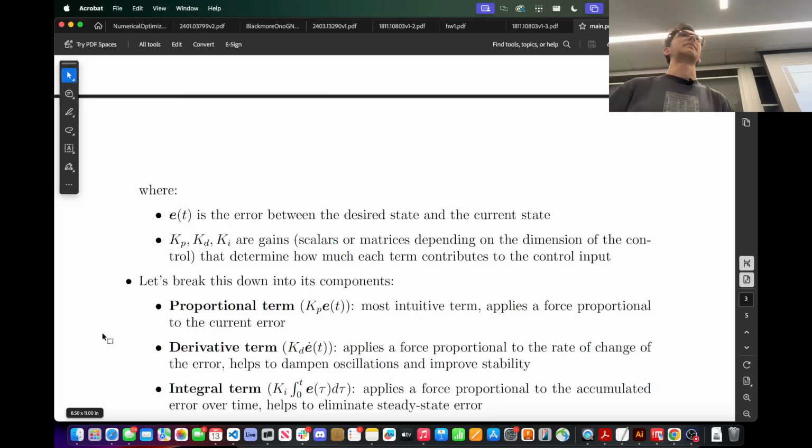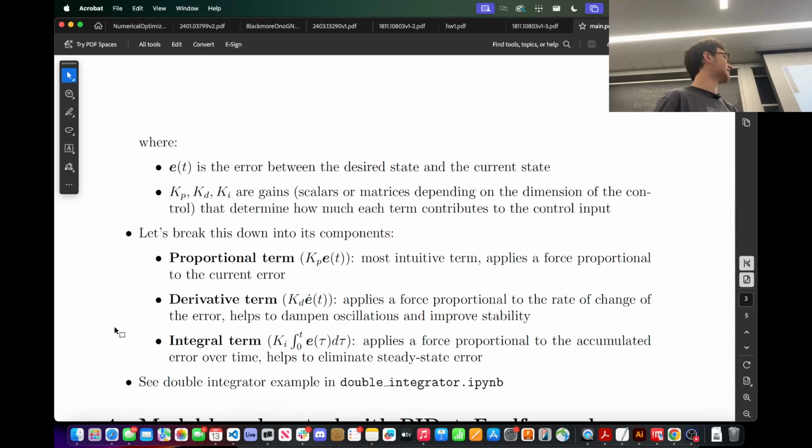You can do a min-max on the integral term. There's a lot of heuristics that people use. You can do a min-max on the actual value of the integrator. You can do what you said, which is you only allow it to act at certain distances or at certain error margins. So yeah, there's a lot of heuristic stuff that you can do if you determine that you need an integrator. But there are some ways that you can try to get around using an integrator, which we'll talk about. But in general, these are the 3 magical components of a PID controller that you'll see very frequently.